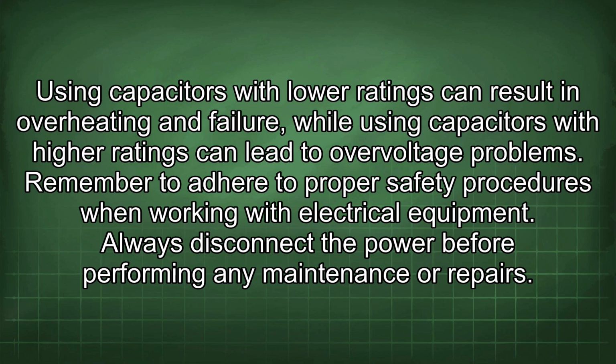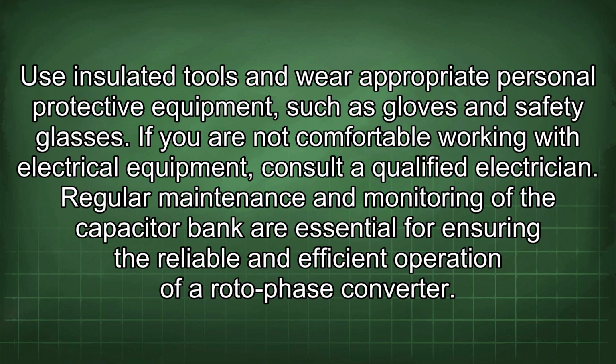Remember to adhere to proper safety procedures when working with electrical equipment. Always disconnect the power before performing any maintenance or repairs. Use insulated tools and wear appropriate personal protective equipment, such as gloves and safety glasses. If you are not comfortable working with electrical equipment, consult a qualified electrician.